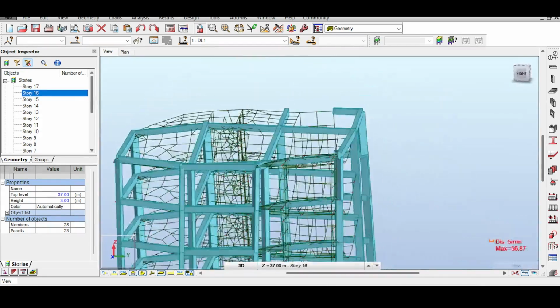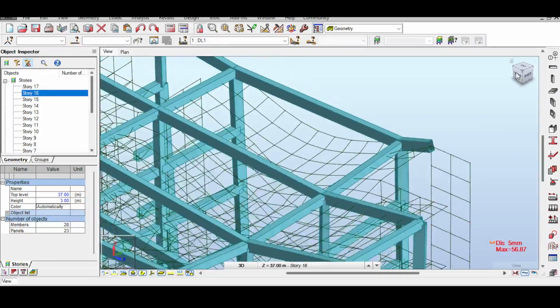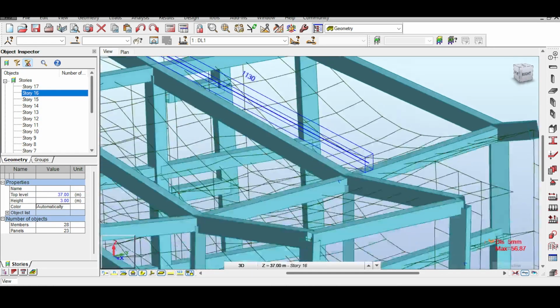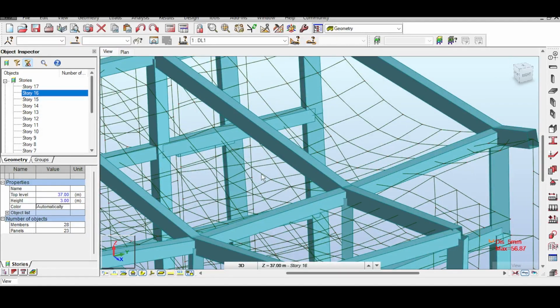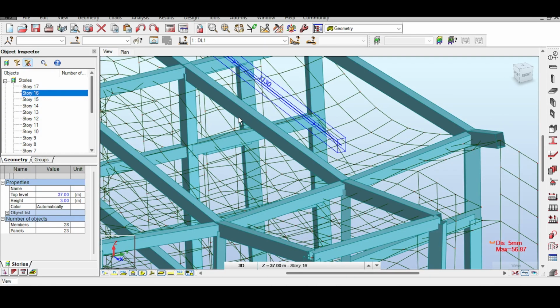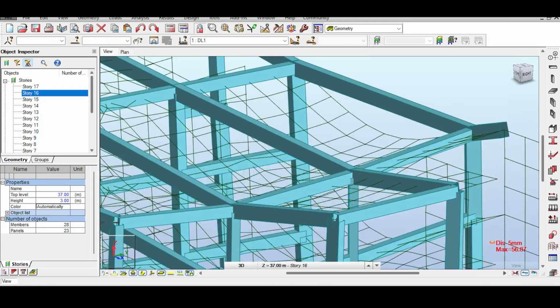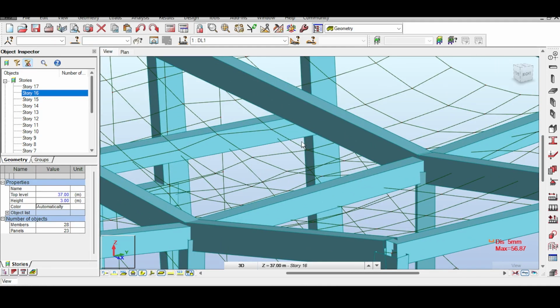That's good news. Now, don't worry that there seems to be a disconnect between the beam and the slab. It is just a graphical issue here, and I can tell you it's a graphical issue, because you see the slab has multiple points in the center which are discretized and can deflect, whereas the beam in the graphical engine is only deflecting at its edges. And I can tell you that because I program finite element programs myself. You can kind of see the effect of the beam by looking at the deflection. You can see that the slab is stiffer just on the beam line because the beam exists,